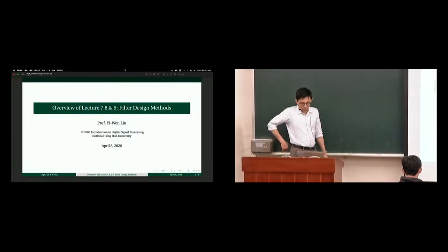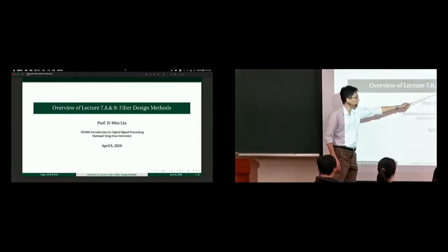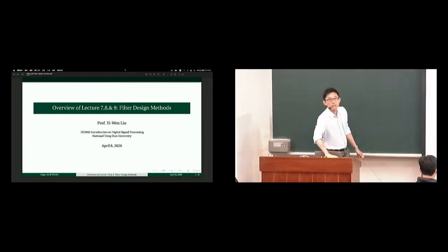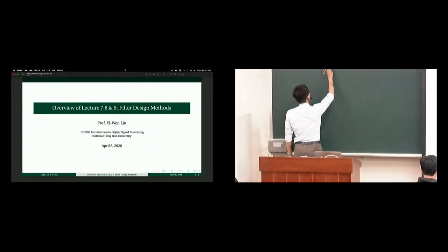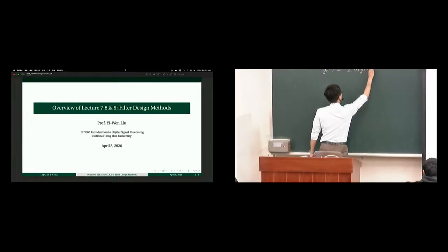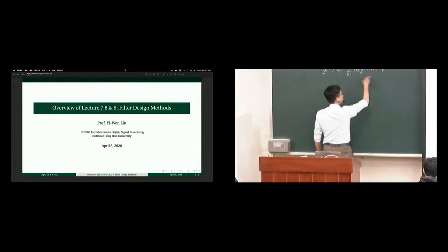All right. So today we will shift to the next topic, filter design, to design something. So design versus analysis, to design, to analyze. Previously, we've been studying this system, y[n], which can be calculated iteratively by looking at past samples, like this: a_k y, the kth sample in the past. So k could be from 1 to, let's say, finitely many M samples, and form a linear combination like this.